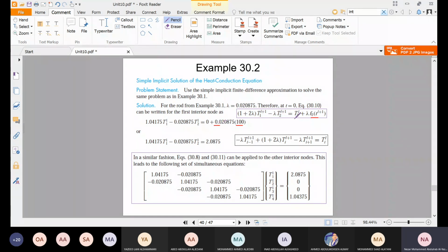And again, these unknowns at the beginning are zeros, or sometimes we use some values from a table. Depending on the table, we use the initial values of the temperature at these nodes. Initially, we can start from them. The easy way, the simple way, is to start with zeros. So this is the temperature for this node initially, and this is the lambda.